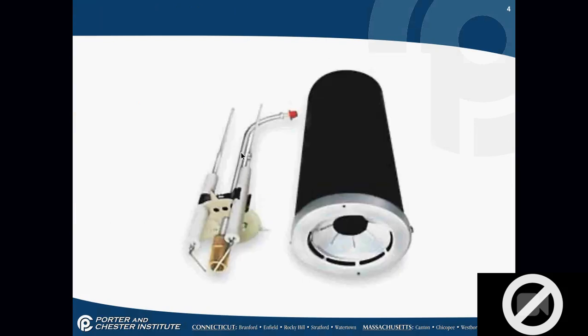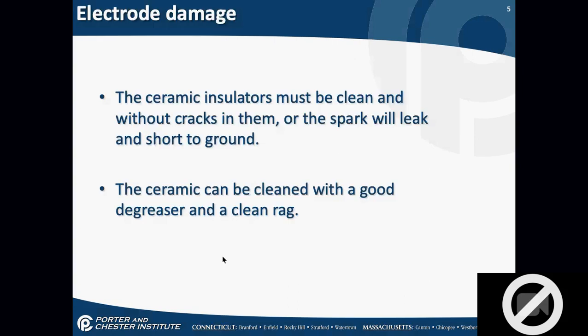So when we look at the complete electrode nozzle assembly, right here is where the electrodes are held in place. The tips of the electrodes come out here into the path of the oil, because right here is where my nozzle gets put. So we clamp the electrodes in. This is a clamp that you can loosen and tighten in order to turn and adjust these electrodes. You're going to spend a lot of time on electrode adjustment in shop, and occasionally you're going to want to toss one across the room because they're tough to get adjusted. There's an art and a science to adjusting these things.